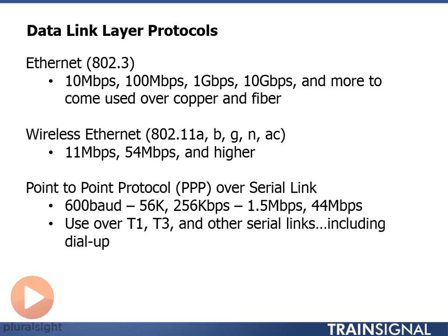They figured out how to convert the analog signal of the phone communication into a digital signal so that they can send that over long distances. And the difference there is that digital signals are much easier to clean up and repeat than an analog signal is. In the 50s, we built this T1 technology to transfer telephone calls over long distances. And then in the 70s, 80s, and 90s, we began to use those T1, T3 technologies to connect data networks together across long distances.